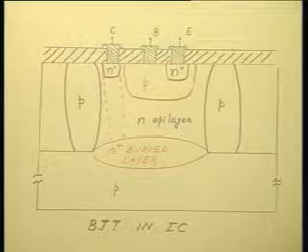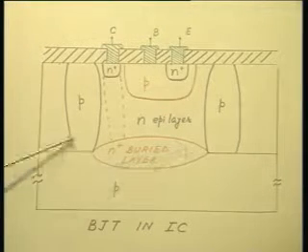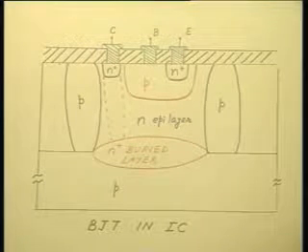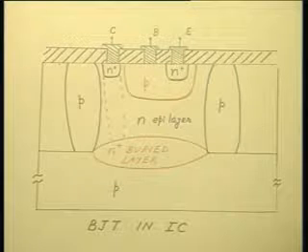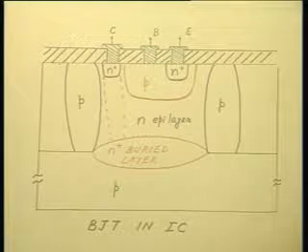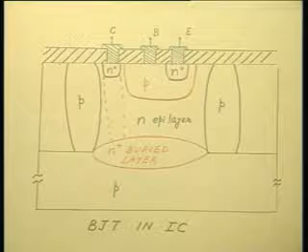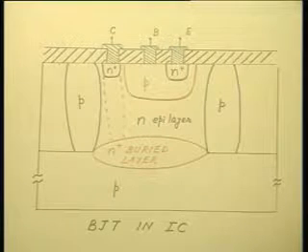substrate. Okay. And then you know the first step was in forming this N plus buried layer. Of course, it has all the associated oxidation and photolithography to define the active area, but the goal of the first few steps was to realize the N plus buried layer, and this N plus buried layer is needed to cut down the collector resistance. Okay.